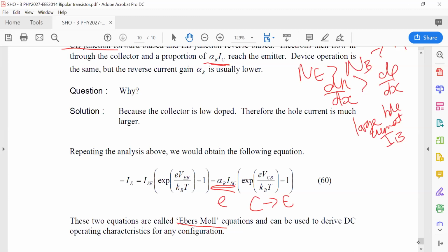both for NPNs and PNPs. Okay, so as I said right at the beginning, the three main things to determine your good operating characteristics are going to be this doping level here, the device dimensions, having a long emitter and collector and having a shorter base, and also having a very narrow base width. Okay, so those are the things we need to think about in order to get the current to be amplified at the output relative to the voltage or current at the start of the device.